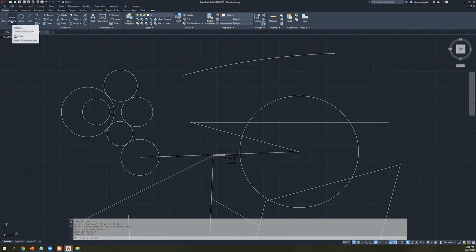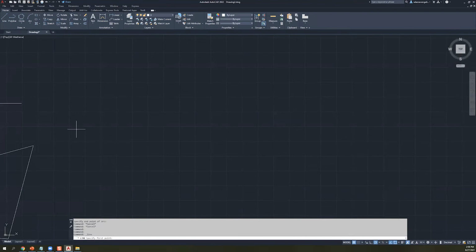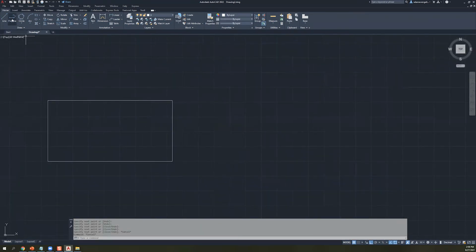There is something called a polyline, which you might be interested in as well. So let's talk a little bit about polylines. To start, I could turn on ortho mode over here, and maybe I just want to draw a square, looking for those horizontal points. You see how I came to that first corner to get that reference so I could draw horizontally? That's great. I'm going to do the same thing, but with a polyline in particular. They don't have to be exactly the same in this case, but something like that might be cool.